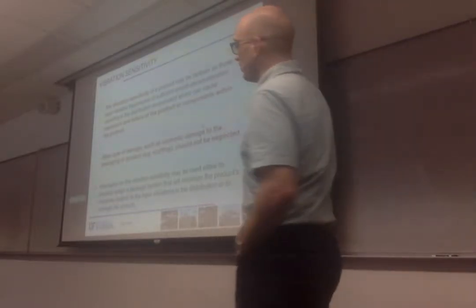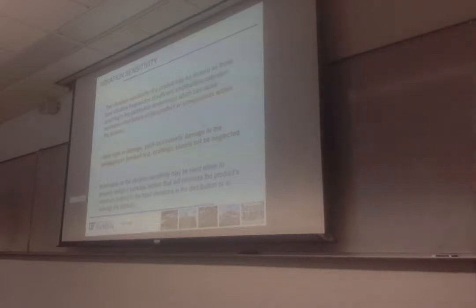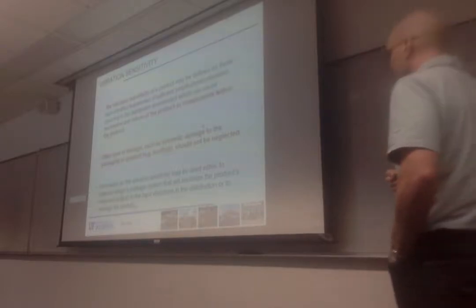Vibration sensitivity. When you hear this term, you need to understand that it is defined as those input vibration frequencies that have sufficient amplitude and acceleration, and that occur in the environment, that can cause resonance or failure of your product or a component within the product.